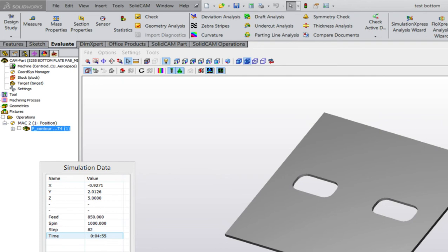It also takes into account the rapid moves. So that rapid speed has to be accurate with the machines that we have. It probably is not, because I don't think we went into our post processor, clocked our speed on our machines, and then hard coded the rapid feed rate of our machines. So it's probably off a little bit on the rapids, and it's also off on tool changes. It's going to guess at a tool change time based on what it thinks that the machine can change its own tools.